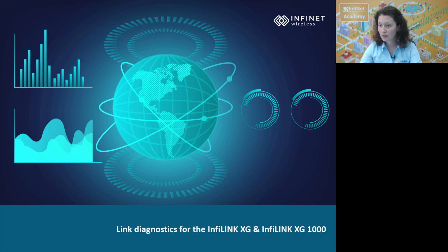Next, also Nick is asking about the RSSI and the occupancy. Here in the case of the XG device, we do not talk about occupancy. We only have visibility of the RSSI level. So when we have interferences, you should directly see an increase in the RSSI level for the specific frequency. It does not show you the occupancy like in the case of the R5000 devices.